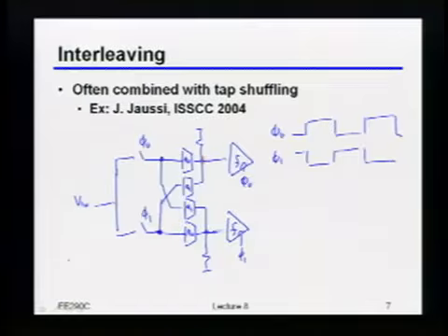That's a great question. It strongly depends on how you're setting these coefficients in the first place. If I have an adaptive algorithm controlling these coefficients anyway, as long as I can control those 2 independently and get error information from both of them independently, I may not really care that they're physically 2 different structures. But if my adaptation algorithm can't tell the difference, meaning it can only give me 1 piece of error information, then you'd really have to make sure that they match sufficiently precisely. So that's another thing we'll talk about: depending upon how exactly this is done, it may be fairly easy to guarantee that matching, or it may be quite challenging.